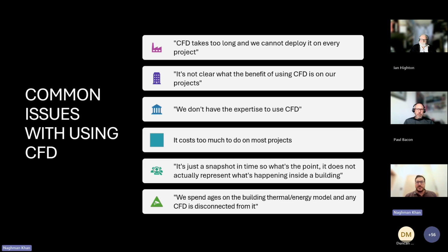Yep. Right? When you're doing your energy thermal model, we're used to the hourly simulation zone by zone and looking at hourly weather data. Now we have hourly CFD, which is very interesting. And it might take people a while to get their heads around this. I think it needs to be explained a few times over, right? Because you can see an animation from a steady state CFD. Doesn't mean it's dynamic. That's just an animation, right? From the steady state and static results, to Paul's point.